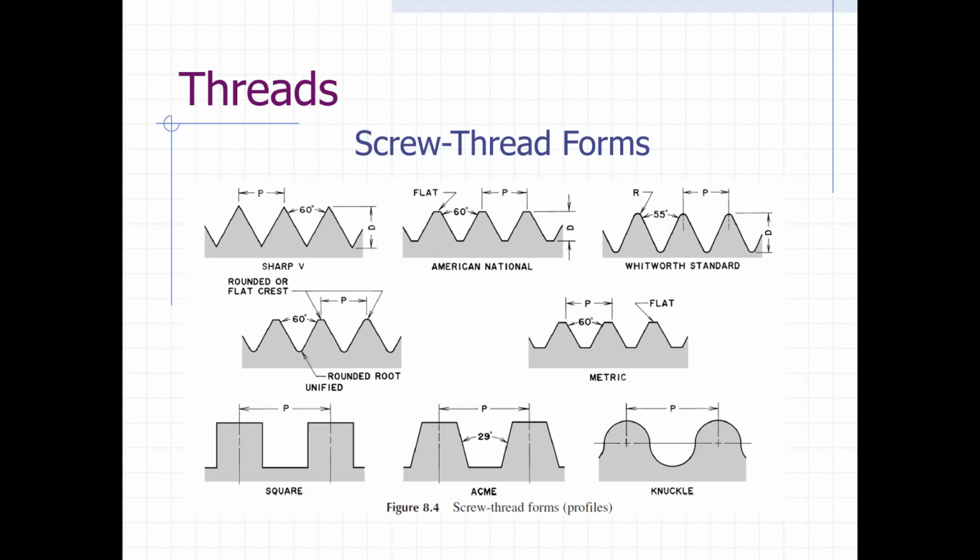But you see those on vises, and if you look at the 3D printers, a lot of those things that are moving those platforms up and down, that's going to be an Acme type thread. So it's designed to put more pressure on. If you put a lot of pressure on that 60-degree thread form, what's going to happen? It'll strip, right? You'll just pop the threads right off the cylinder, and now you got a big mess, right? So these Acme threads or square threads, those are designed to apply a lot of pressure.